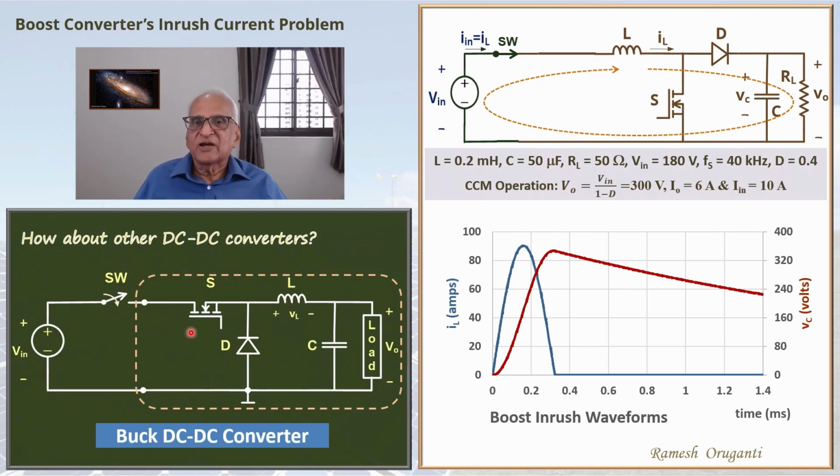And you're likely to have some inductance here because you're connecting the source to the buck converter. So you will have some wiring inductance LS. Now you see what the problem is. I'm having an inductor LS. It may be 20 nanohenry, 30 nanohenry. We have a series switch S, which is switching on and off at the switching frequency. Inductance current being interrupted by the switch will give rise to a large spike in the voltage. So the voltage at V dashed in will not be a nice DC voltage.